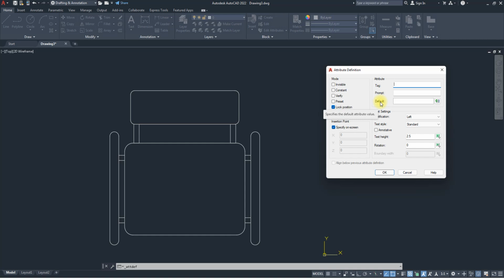Then you have another door, a glass door, and you can have different sizes of that glass door. It doesn't change the fact that the glass door is still a glass door. You understand? So in that case, flush is a constant attribute for every instance you are making. Am I making any sense? In the same way, if you make an attribute constant, then when inserting every instance, it won't allow you to change the name because it's a constant attribute. You understand?